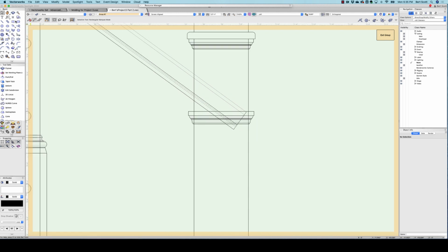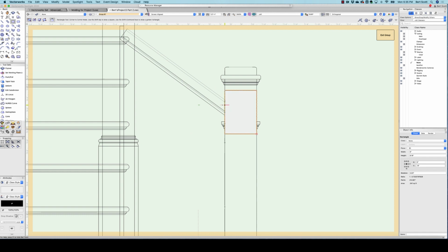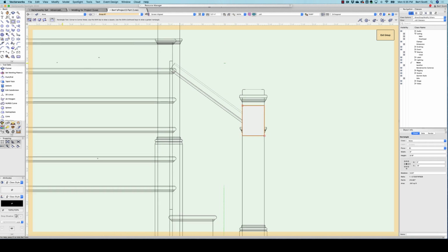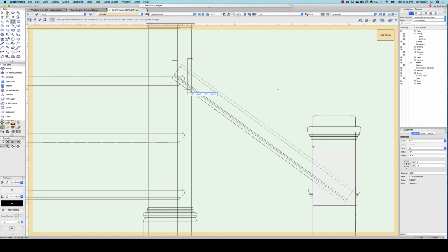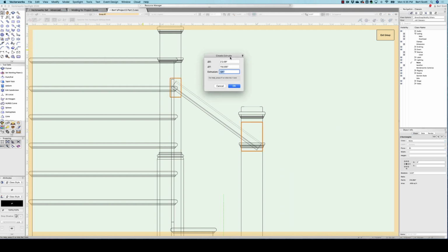So we're going to do a solid subtraction. So I'm going to draw a rectangle. Whoops. See, I'm still in the wrong mode. Back to the first mode. I'm going to draw a rectangle here that lines up with the left-hand side of this newel post and encompasses all of the handrail that's under it. And then I will draw a rectangle here. Then I'm going to extrude both of these rectangles. Model extrude, let's try 4 inches.